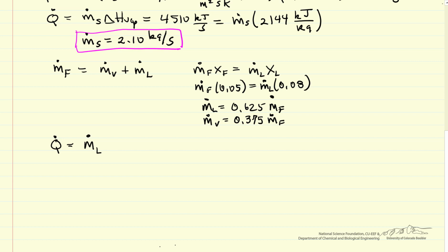Some of it is going to end up as liquid at a different temperature, and so the enthalpy of that liquid at 99.73 minus the enthalpy of the feed, these are per kilogram, that's one of the terms. And then the rest, water that evaporates, the enthalpy of that water at 99.73 minus it came in the feed as a liquid, so the energy to evaporate it is there.